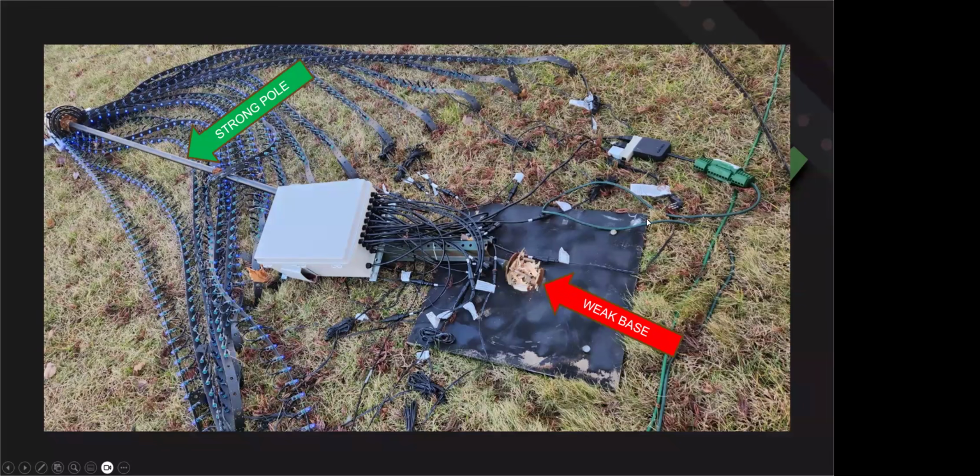Connections are very important when you're designing a mega tree. You want to make sure that you have something that's going to be sustainable. It's embedded in there. It can take some of the load, most of the load, in fact. You definitely want it holding up for when you're erecting the pole before your guy wires are installed on there.